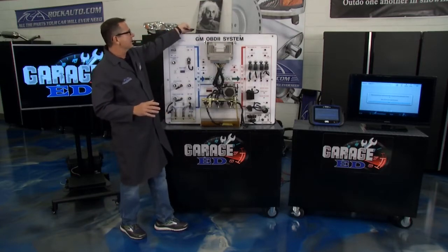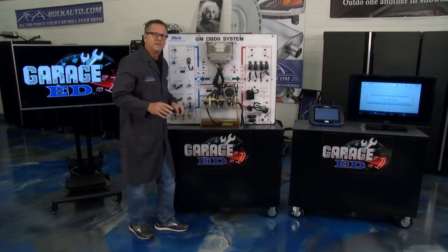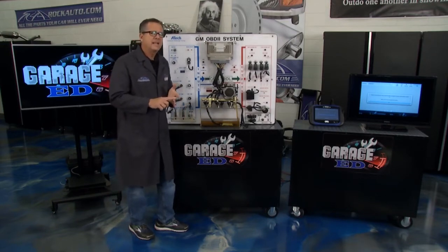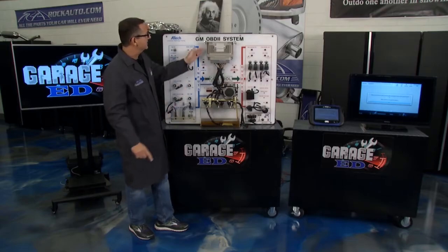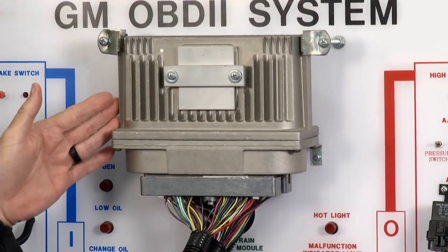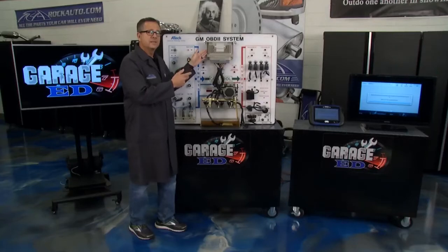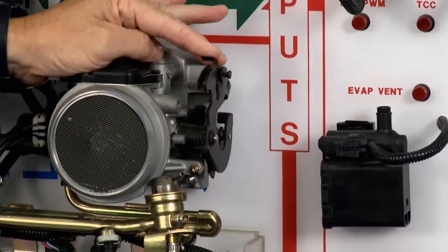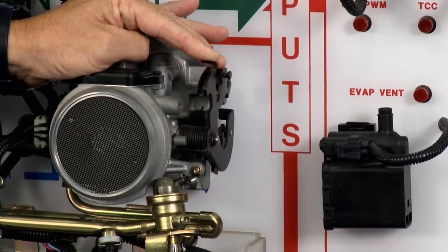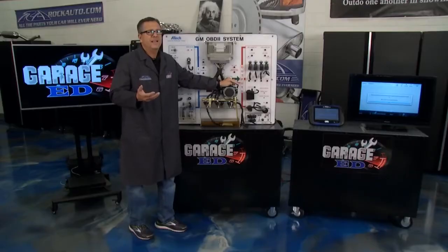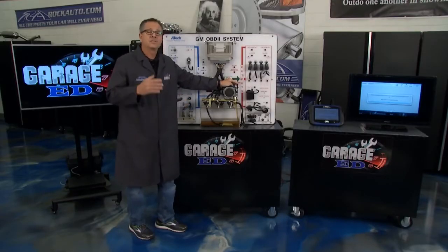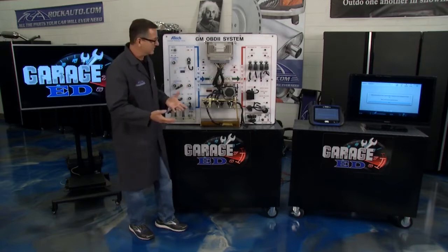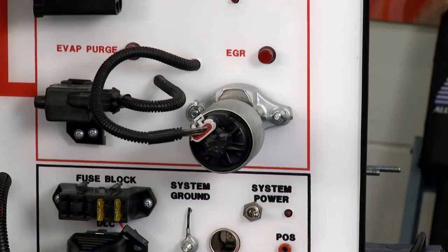But these sensors also employ a couple other strategies, and I want to talk about it right now. They use 3 things: integrity, rationality, and obedience. Integrity is pretty simple. You got the computer right here. When you turn on your key, it sends a signal out, and if it sees a signal come back, that's a pass. Rationality is a little bit different. If I take this throttle and go wide open, that should be a massive amount of air going through, and the RPM should be up around the 4,000 or 5,000 range. If it's not, it doesn't pass the rationality test. Last is obedience. What is that? If we ask the computer to open up the EGR valve down here, he should see a big hole in the intake manifold, and the MAP sensor should respond accordingly.